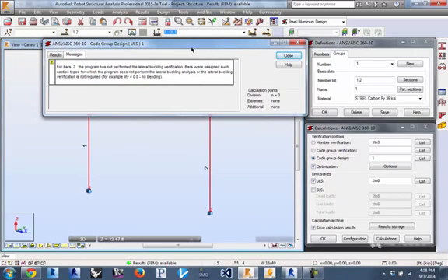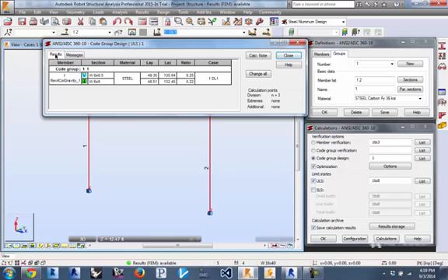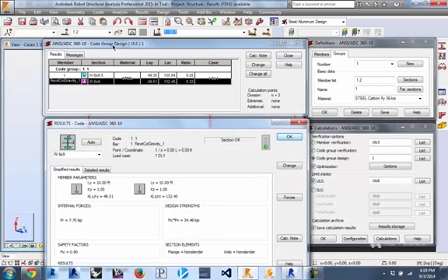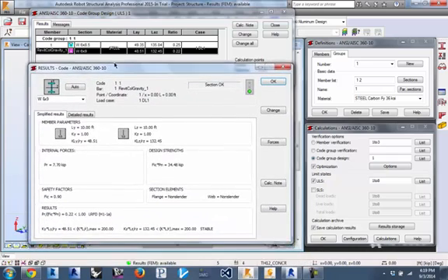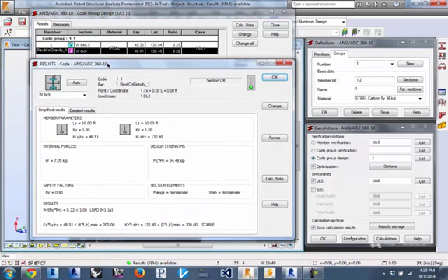So if you are like me, I didn't place any bracing in this, so it's already recognizing that. So it didn't run any lateral verification, but we do have results. This is just a warning message, so we do have results. And we see that it ran the analysis on this, and we can see what it's giving us. When we update this, we'll be able to put multiple columns in here and see which ones work and which ones don't.